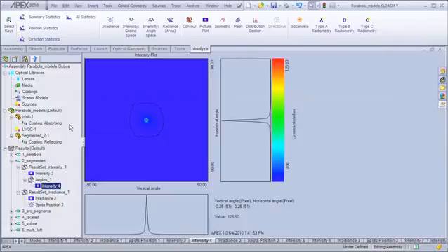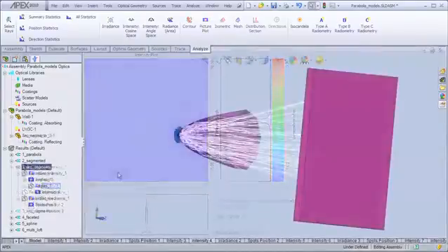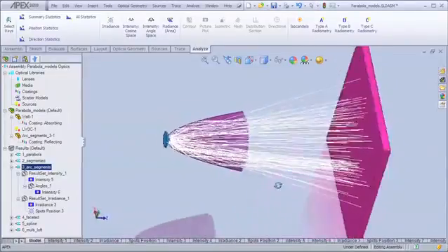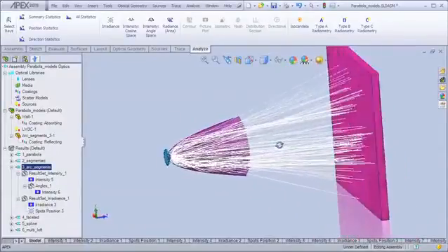If we look at the angular distribution, we see indeed that the energy distribution is all coming out at a very narrow range of angles, which means we could use this same light source over a long distance without significantly reducing the energy distribution. For this design, what we've done is maintain the basic parabolic shape to the curve, but instead of sweeping it across a circle, we've defined a polygonal output face, and we're simply sweeping the curve relative to that polygonal section. So we're sectioning our curve based on the number of facets in the polygon.